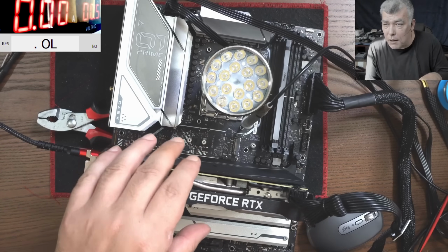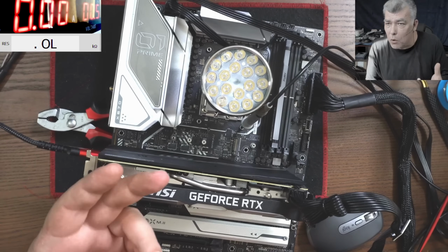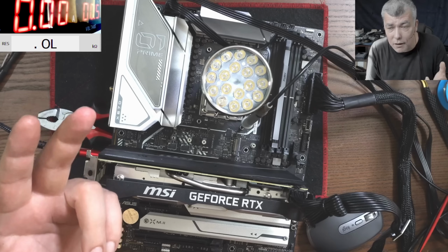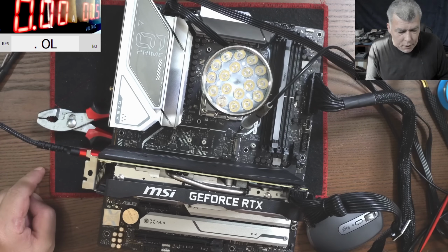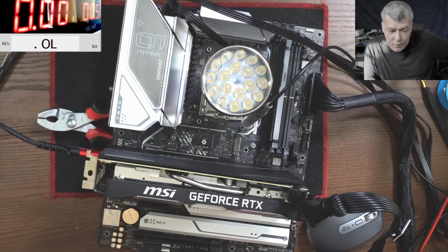But have in mind, in this case, what do we have? We have an unknown MOSFET, or MOSFETs. Can be one, can be two. Not sure about that. And we start with, okay, what is this doing? We don't know what it's doing, but it's taking some current. It has 2 pins for plus, 2 for minus. Then you have to find, like in this case with this MOSFET, the input and the output to see what it's doing. The input, you know, is 3 volts. The output looks like it has to be around 1 volt.